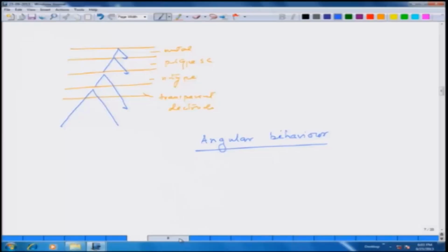In this course we do not go beyond this point, but we need to keep this in mind. So, to summarize what we have done in optical properties, we have looked at what is the reason for optical properties, just like we have done for electronic structure. We have looked at how light interacts with the material, the basic parameters that decide the reflectance, transmittance, the inhomogeneities, the roughness of the surfaces, all those things which add up to scattering, that one has to be aware of when one is talking about optoelectronic devices. And in addition to that, one has to be aware of what would be the overall effect of these different layers, when we have them in thin film form, on the optical response of the device.